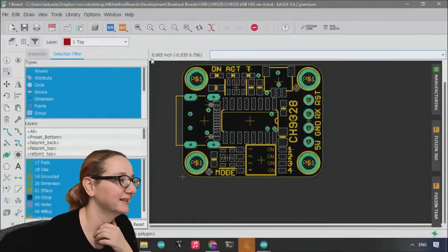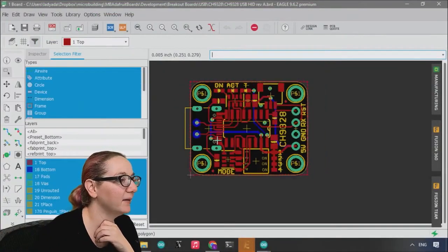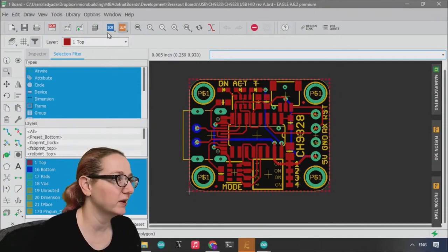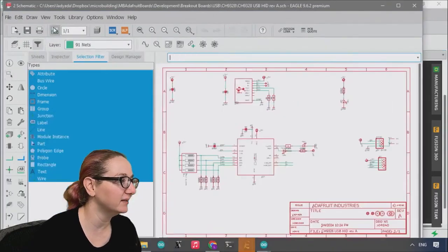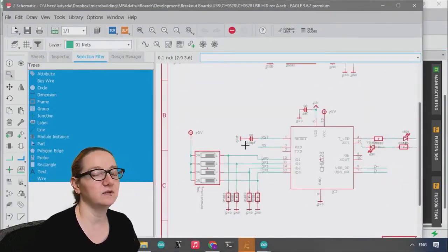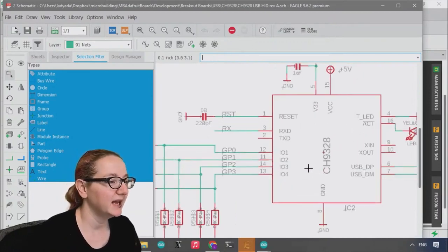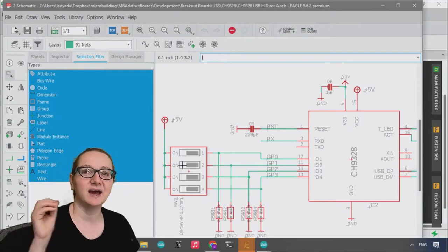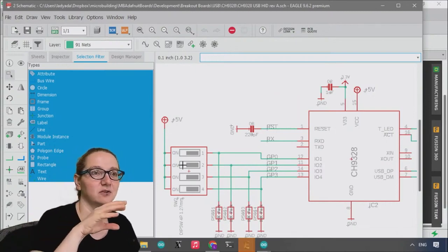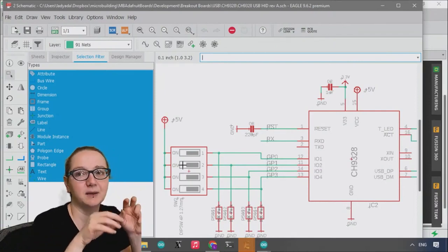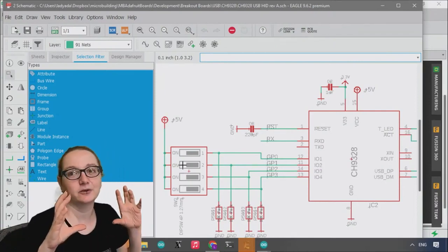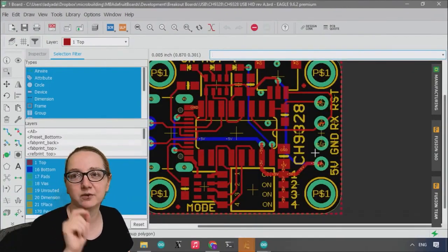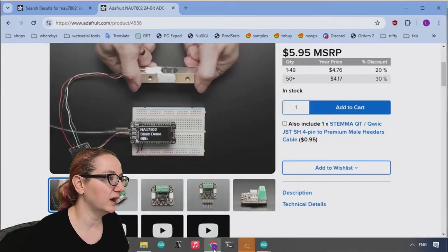Oh, yeah. Okay, so this week, I'm working on a bunch of boards, and a lot of them have modes or configuration bits that you want to set. Like this CH9328 is a UART to USB HID chip, and it has 4 I/O pins that you can select different modes. So like one mode is when it gets ASCII characters, the ASCII characters are typed by the keyboard, and there's another mode where you send hex characters instead. And normally what I would do is have little jumpers or something, and you would cut or solder the jumpers, or you could use through-hole jumpers.